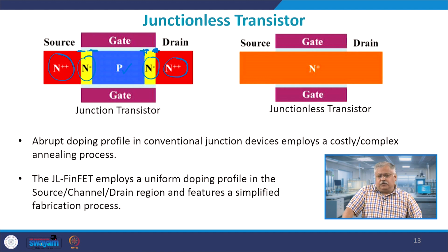which means that if you look at the right hand side figure, it is a junctionless double gate transistor, where this is the top gate, this is the bottom gate, and you see the whole of it, there is nothing like a channel being formed there, the whole region is basically N plus region, right. So, there is no junction being formed here. So, it is basically silicon doped with fifth group element, and to generate N plus layer, you can also generate an N double plus layer also.